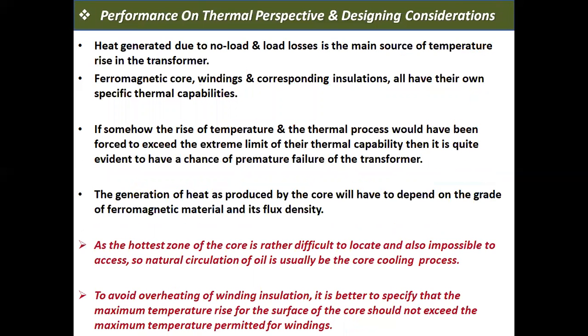Performance from a thermal perspective and design considerations. Heat generated due to no-load and load losses is the main source of temperature rise in the transformer. The ferromagnetic core, windings, and corresponding insulations all have their own specific thermal capabilities.